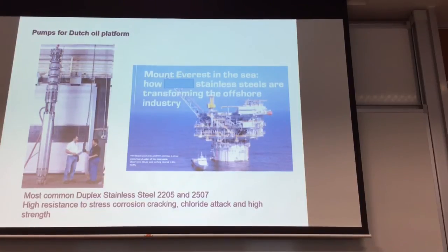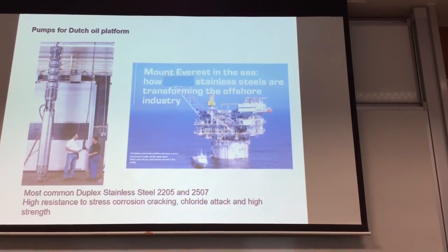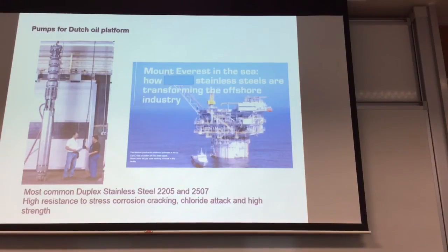And what this means is that corrosion will happen at your grain boundaries. And why do we have stress? Stress corrosion cracking. What happens is normally with your stainless steel you want to apply load to it, right? So let's say you apply a stress to your steel. This corrosion at the grain boundaries will cause a crack. The grain boundaries become cracked. So these grain boundaries become detached from each other. This is your crack. This is because your corrosion is happening at the grain boundaries.